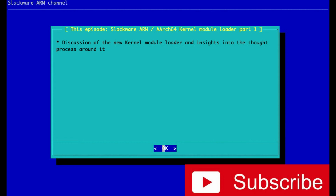But the thing about that is that it's yet something else that I need to go and learn. And as nice as it might be to learn the U-Boot scripting language or look at someone else's for some inspiration, it's still something I'd have to spend time on for no real gain. Whereas what I could also do, and this is the option I was leaning towards, is to put the working U-Boot onto the SD card as a header. So this would be a separate SD card image just for recovery, with a very small initRD on it, because I've already got one, the installer or the OS initRD, and just have it simply take care of flashing and do nothing else.